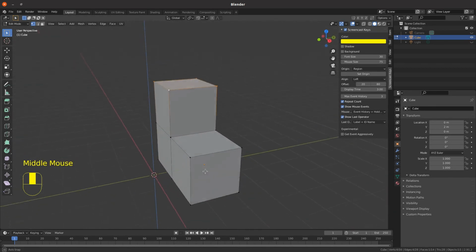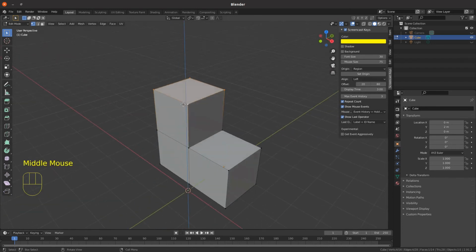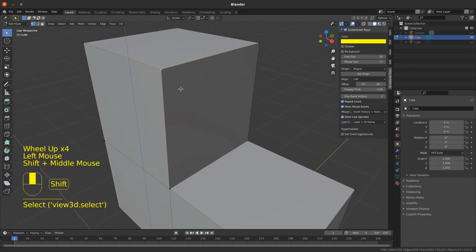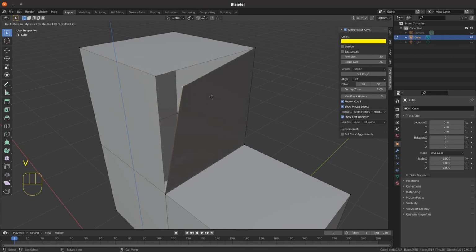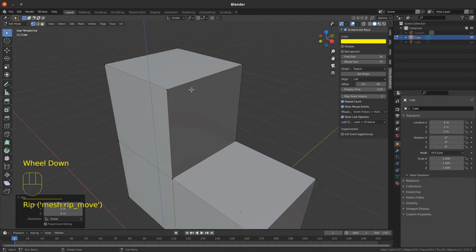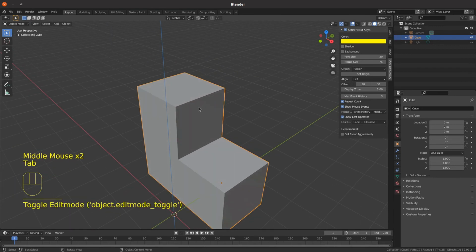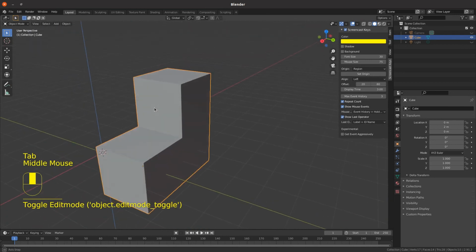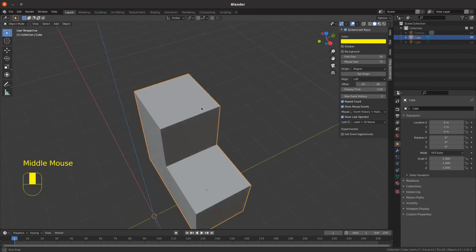I mentioned where vertices are sitting in the same place. I'm just going to press B, split that one face out in that corner. Another thing that can highlight that, and may not do it every time, but in object mode in some angles you'll see an edge coming into the model where it's split.